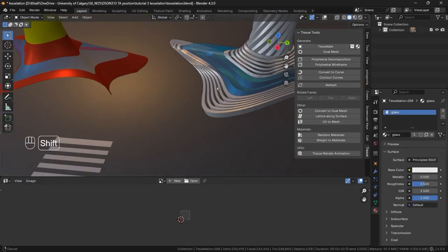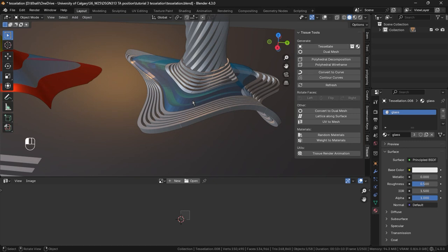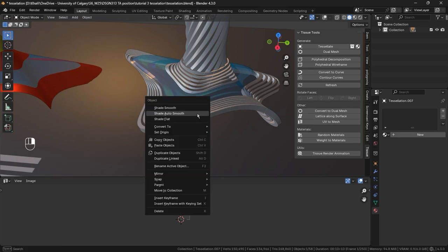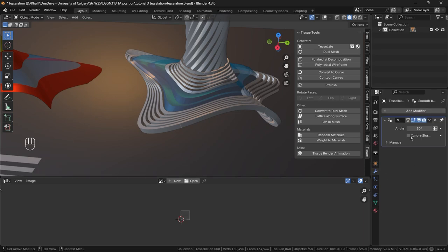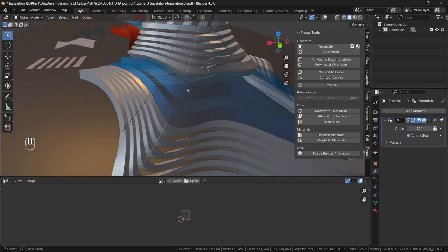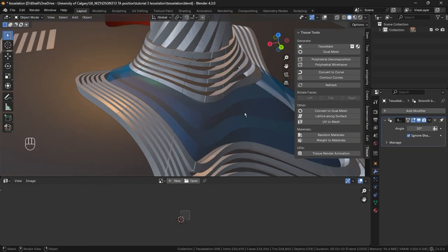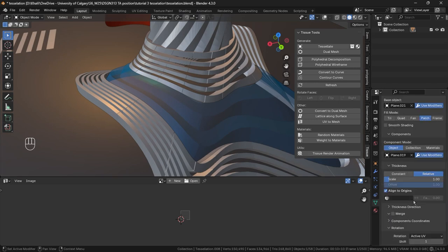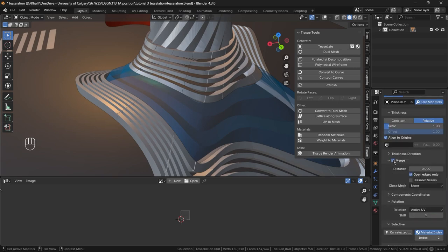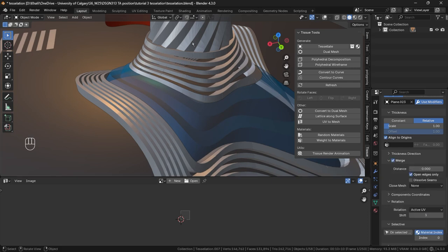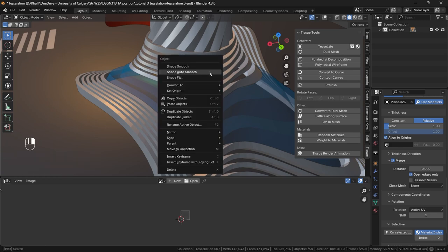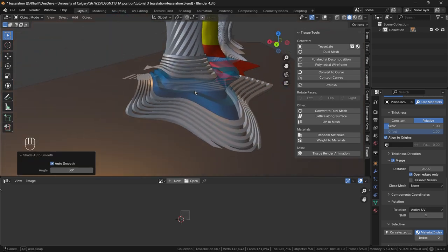If I want to apply the same, oh, I need to auto smooth, auto smooth, auto smooth, and when you go to the auto smooth, I might add some subdivisions to this. Oh, is the merge was not set? Nice, we forgot the merge. We have to not forget the merge, and now it's good. Auto smooth, click right, auto smooth, and now it's smooth.